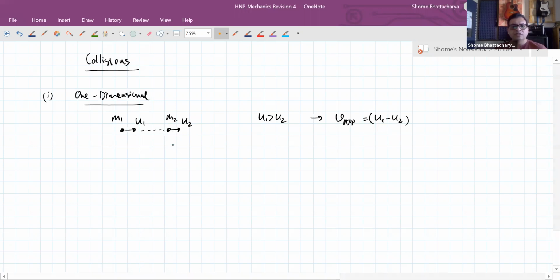this. Okay. Then after impact, so after they come in collision, some kind of collision impulse acts like this, eventually their velocity, suppose, now we are assuming they're in the same direction, but v1 might become a negative quantity also, in which case it will come with a negative sign. So it will be in the opposite direction. So now what will happen is after impact, the separation velocity becomes v2 minus v1.